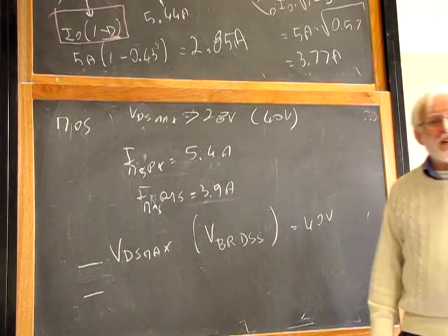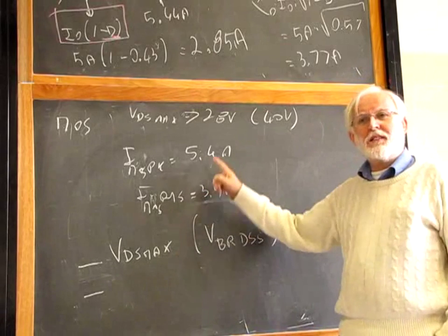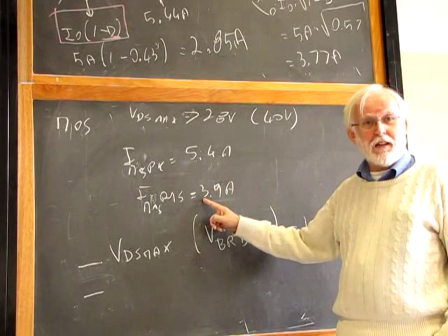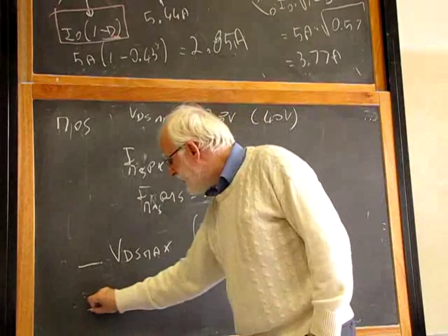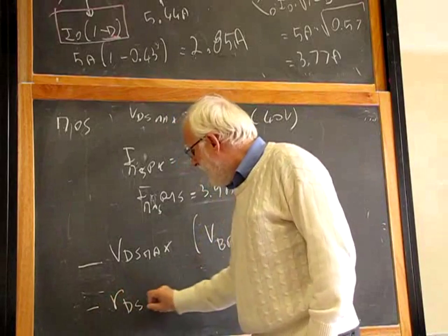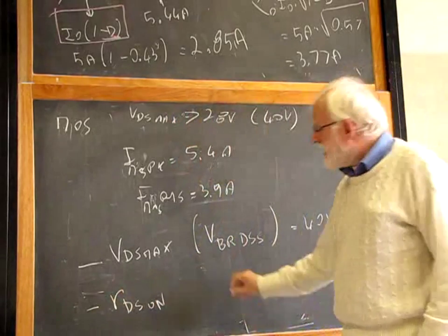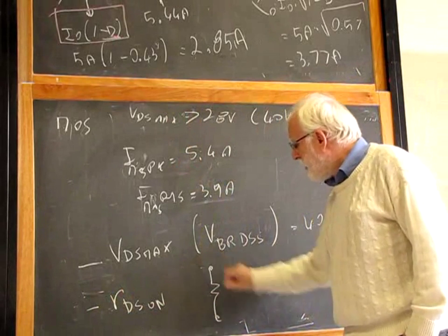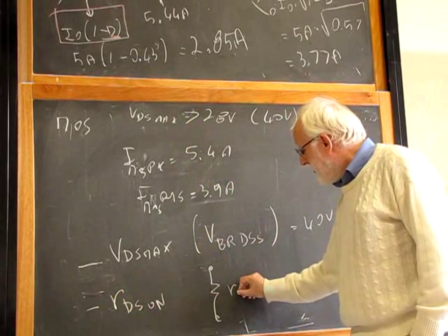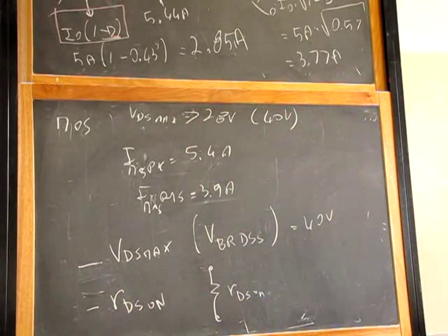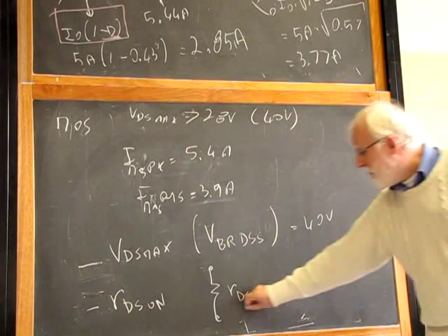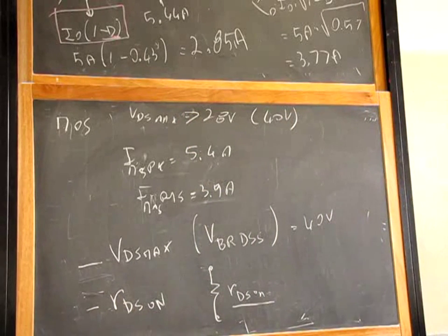And then, usually, in power electronics, nobody cares about the RMS current and the peak current of the MOS transistor. The important parameter is a different one, the so-called RDS on. That is the resistance the channel of your MOS transistor has during the on phase. During the on phase, your transistor looks like a resistance. The value of this resistance is given by RDS on, and is an important parameter in your design. You have to specify these two numbers.